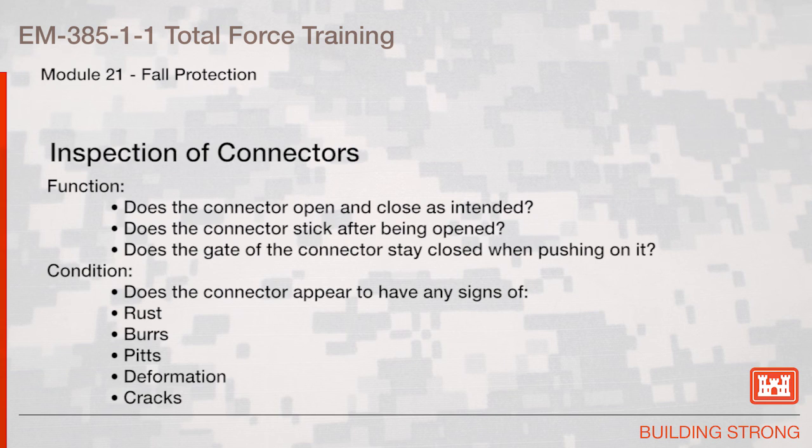Inspection of connectors. Connectors should be inspected for the following. For function, does the connector open and close as intended? Does the connector stick after being opened? Does the gate of the connector stay closed when pushing on it? Condition: does the connector appear to have any signs of rust, burrs, pits, deformation, or cracks?